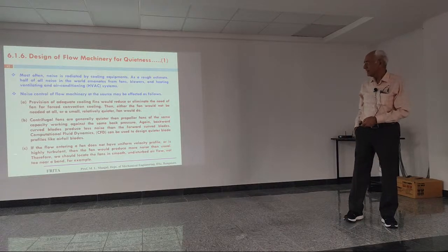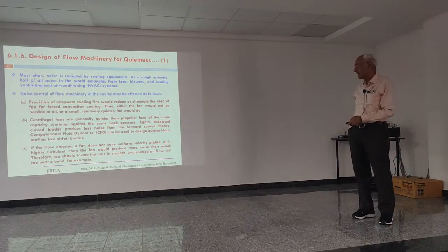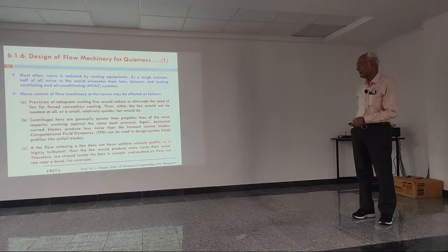If the flow entering a fan does not have a uniform velocity profile or is highly turbulent, then the fan will produce more noise than usual. Therefore, we should locate the fan in smooth, undisturbed airflow, not too near a bend, for example.